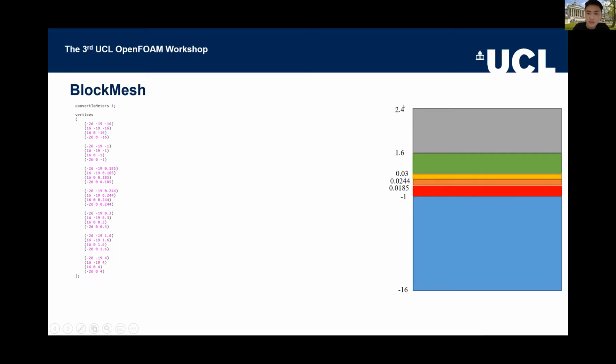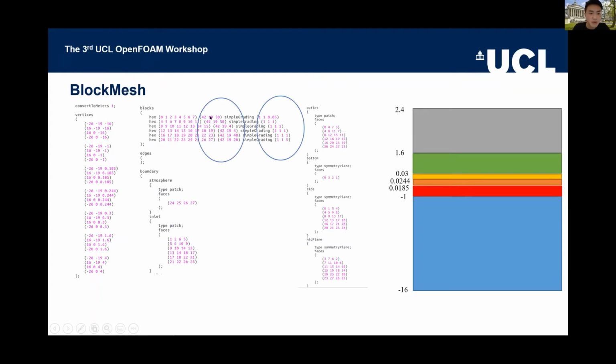In this case, blockMesh divides the domain into many different blocks, and then you can define different mesh density here. If you see block 1, you can put here the cell counts, for example 50 and 50 in x and y, and 40, 20 along z. But x and y are always the same.